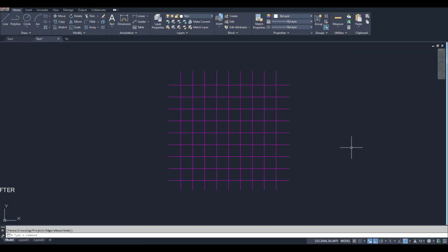Okay, so here's another example. Let's say we wanted to trim this line so that this came all the way back to that line there. We just want to keep this last little bit. So we click on trim. My cutting plane in this case is going to be that line there. Press Enter and click on the line to bring it all the way back. Enter again. Let's click on trim. Let's say the second line down, we want to come back to that line. So that's my cutting plane. Press Enter and click on the line to trim. It stops at the cutting plane that you selected.